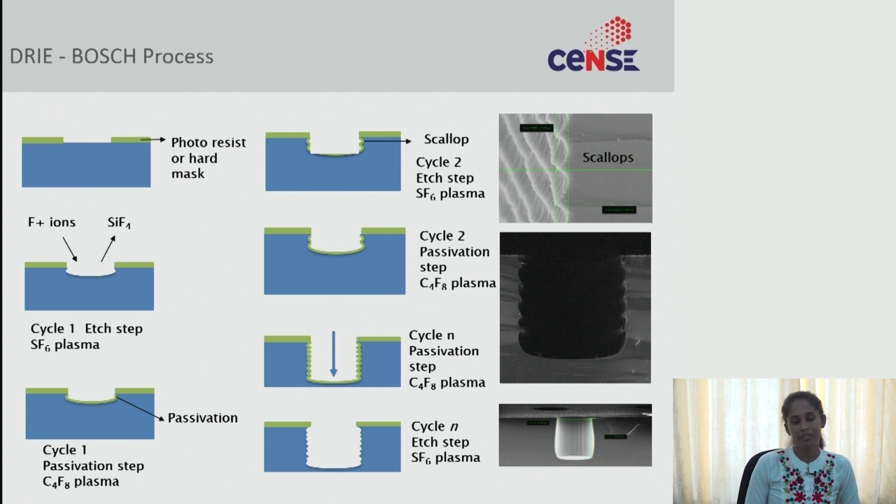So how can we achieve such a deep etch? I was telling you TSV means through silicon via. If you have around 570 microns of silicon, we can completely etch through 570 microns of silicon and make a through hole. Okay, so how is it possible? That is because of the Bosch process.